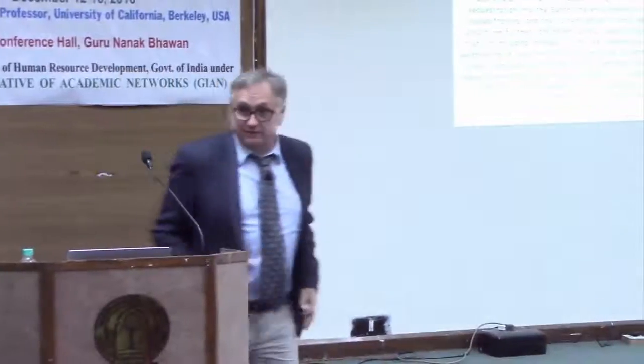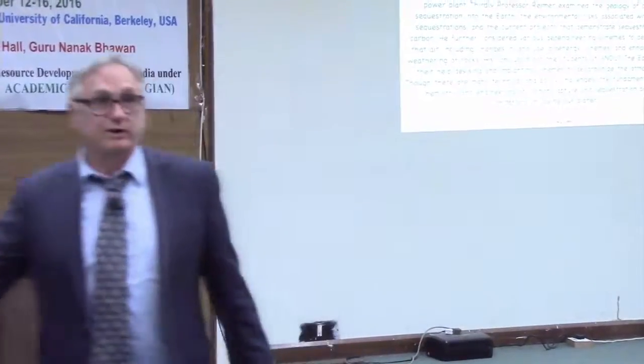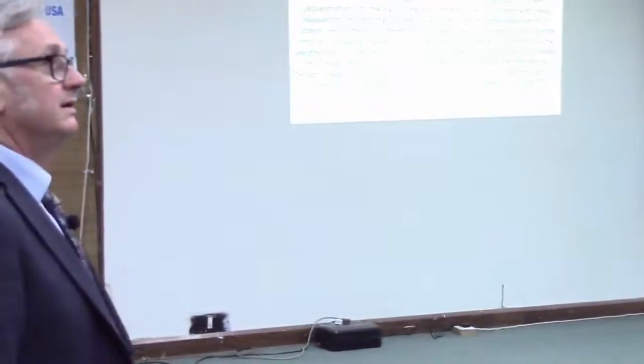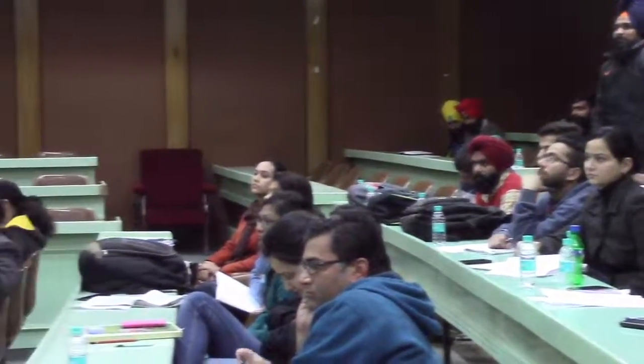So let's call our attention then, in closing, to the summary of our course. Yeah? So for direct air capture, you want absorption to occur at room temperature, 20C, 30C at the most, depending. And you want the desorption temperature to be less than 50C. And that's it. You cycle between room temperature and 50C, and the CO2 comes on and off and on and off.